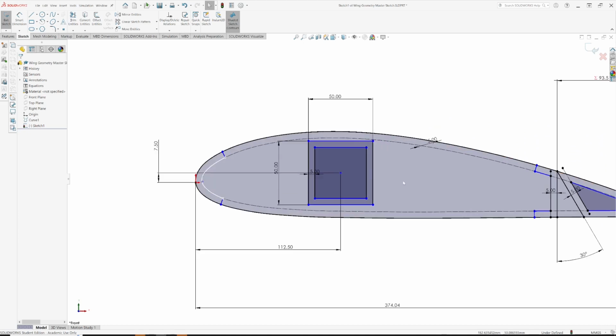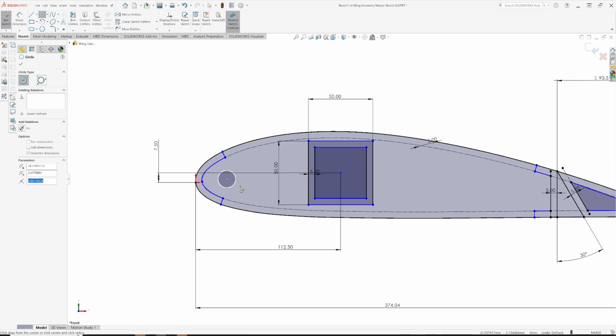This is going to be our rib. Because we're aerospace engineers, we make things as light as possible, and this rib is probably overstrong. I'm not really doing any analysis on it, but there's a lot of material there. So I'm just going to put some lightening holes in. This is more art than science, but I'm basically going to cut some holes in it.